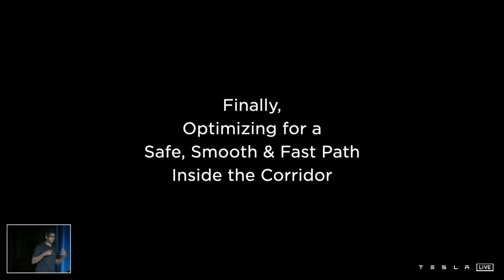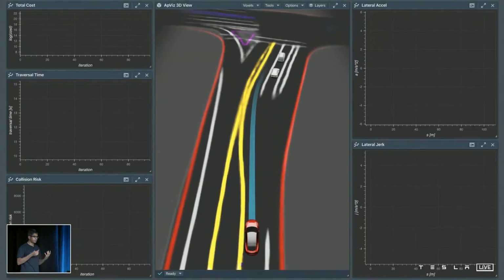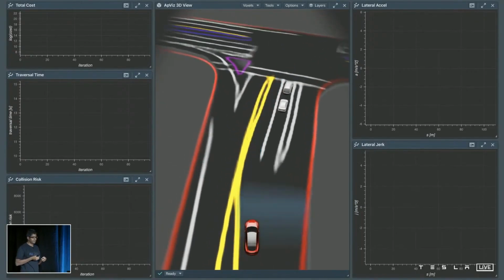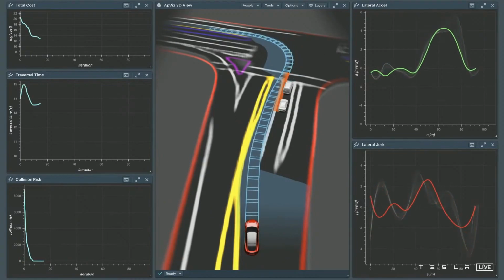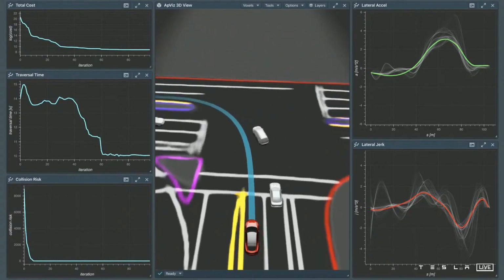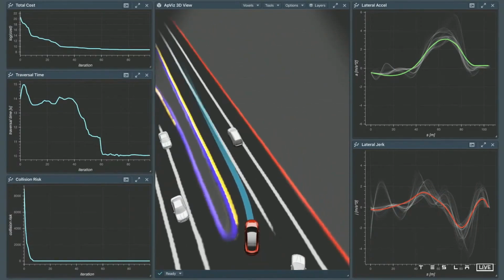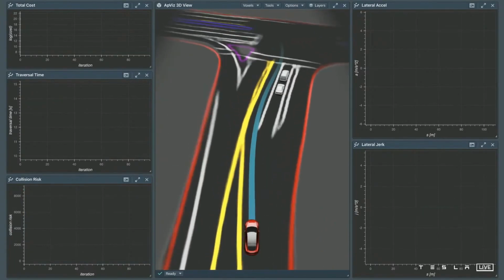So now we saw how the search and planning for other people set up a convex valley. Finally, we do a continuous optimization to produce the final trajectory that the planner needs to take. Here, the gray thing is the convex corridor, and we initialize a spline in heading and acceleration, parameterized over the arc length of the plan. And you can see that the optimization continuously makes fine-grained changes to reduce all of its costs. Some of the costs, for example, are distance from obstacles, traversal time, and comfort.